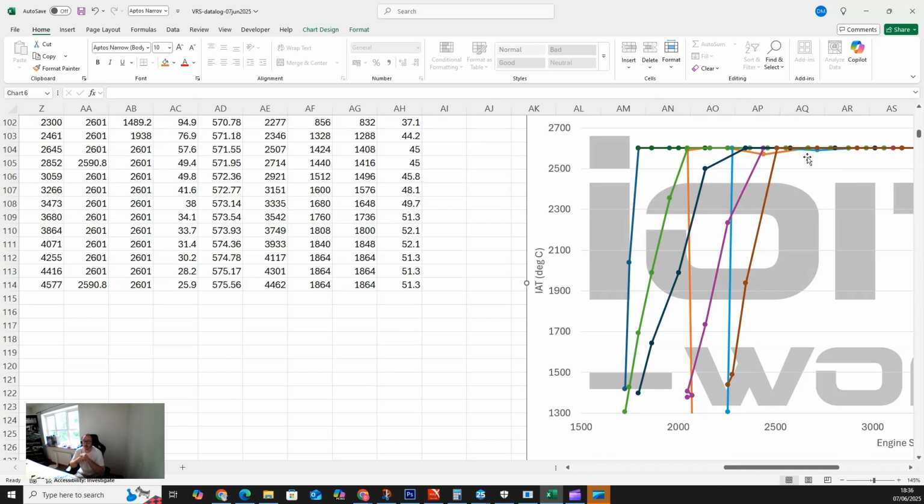So your error would be huge from the actual versus specified. And as the error multiplied into the system, it basically sends a signal to your VNT in this case, to close the turbines down more and more to speed up your shaft speed and get some pressure built. What happens then is you're telling it to close the turbines more and more.